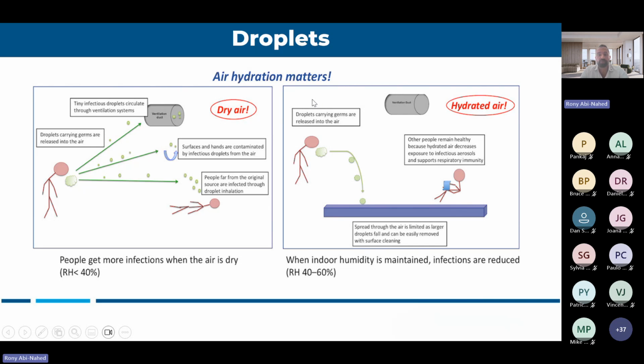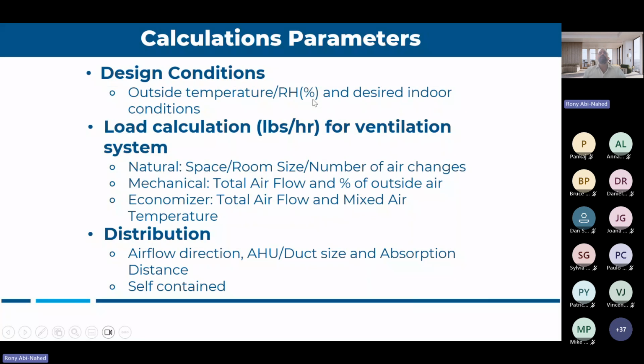And that's why since COVID, there was a lot of school renovation, including humidification, to try and mitigate the virus and bacteria. So that being said, if you want to design a humidification job, where should you start? At first, you need to know, okay, what's the design condition? How much you want to maintain inside the building you're designing, and what's your outside condition, which is like in which area you're designing it.